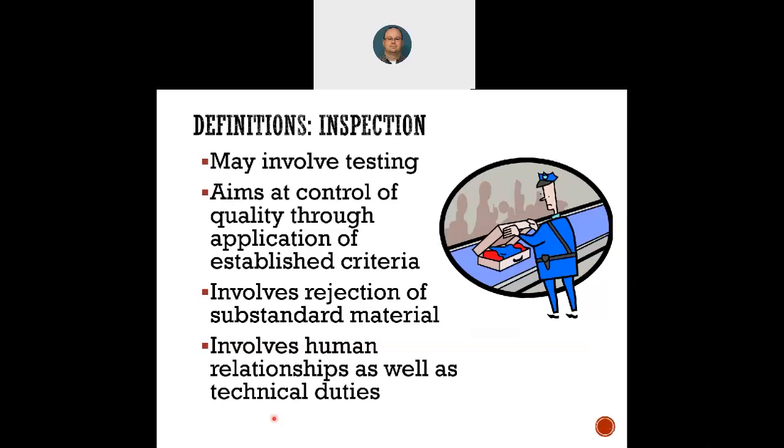Okay, so you don't want to be out there as the inspector being that guy that is the jerk because things don't pass. So you want to be that person, guy or gal, that is willing to help the contractor. Kind of warn them and say, hey, this last slump was really close to our specification.